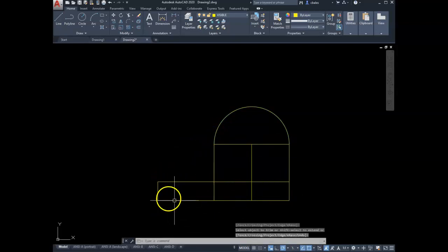Now, you might notice, or maybe not, this looks a little short down here, this 3.5. And what you have to realize is that it's a tricky dimension. 3.5 is only from the back end to the center of that front circular part.